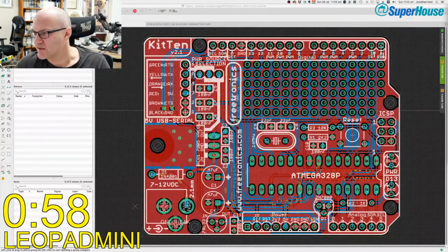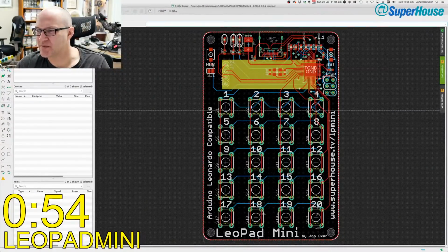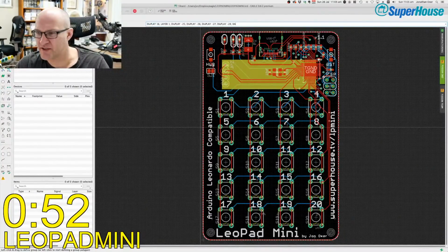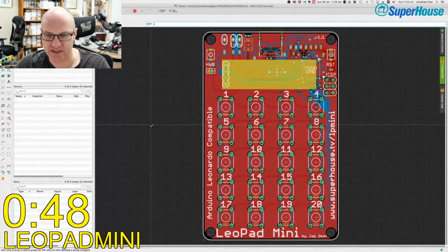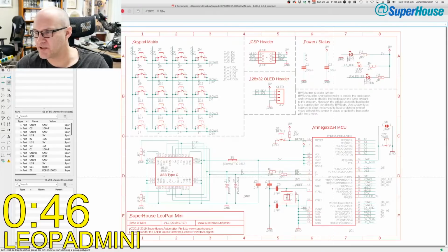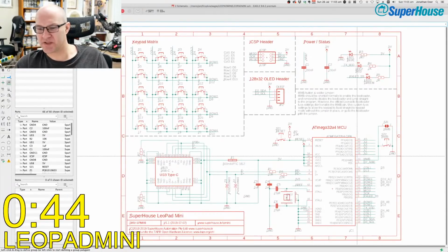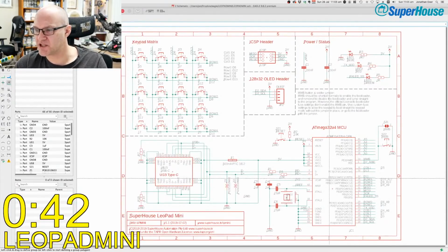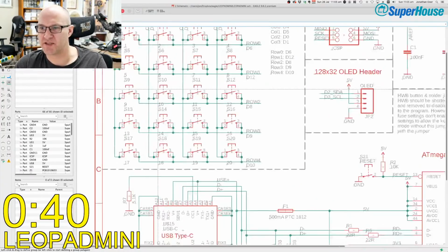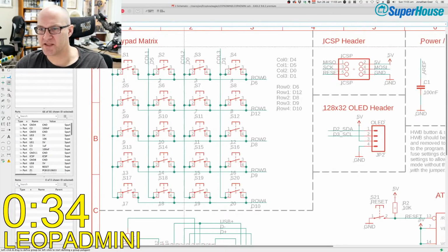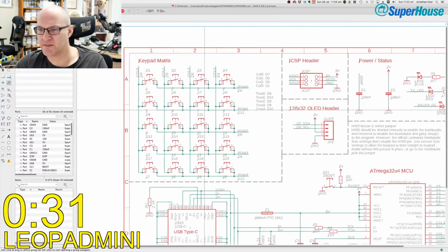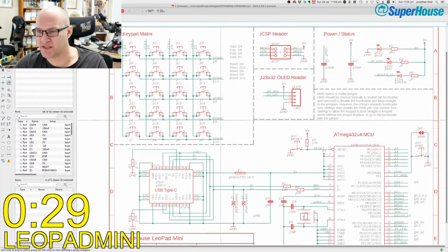Leopard Mini. Oh, this is the thing I was waving around earlier. It's the custom keypad that I use for setting the macros, like what just popped up into the little Eagle console there. It is an ATmega32U4, chosen because it does USB human interface device emulation, and there is a matrix over here. So the keypads are in a matrix with rows and columns, and when any button is pressed, it shorts together one row and one column, and it can then be detected.